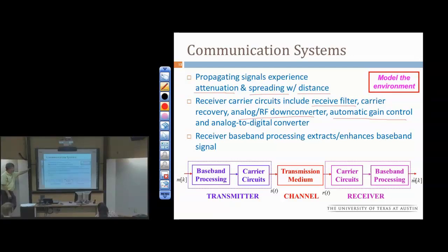Go ahead. Carrier recovery and symbol rate recovery, those are 2 separate things, but they can use the same kind of method. So in carrier recovery, let's say we have an RF carrier like 2.4 gigahertz and the error maybe is 1%. So we have a very small range where that thing could be. For symbol recovery, we have a symbol rate, whatever it happens to be, could be 1,000, could be 2,000 hertz. And we know that in the baseband component, because of pulse shaping, half the symbol rate will be there. So we can lock onto 1,000 hertz. So you go through a squaring device and get that 1,000 to 2,000.